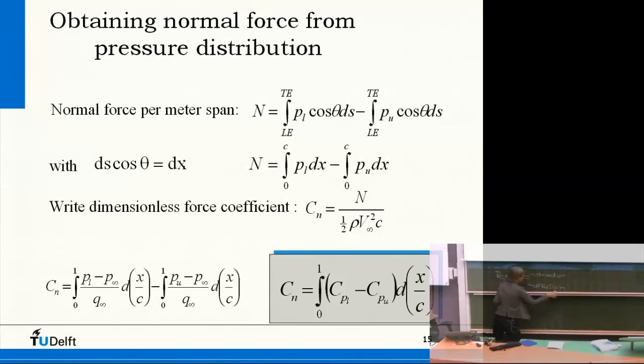Now if the viscosity is dominant, so I have something large below, I have a low Reynolds number. That's typically order Reynolds 100 or so. That is if you, for example, would fly through oil, so the viscosity of oil, something like this length, or a fruit fly, this length through air. Reynolds 100, very viscous. What does it mean? Very thick boundary layers, right? Viscous effects are dominant. Viscous effects inside boundary layers. Actually, large vortices.